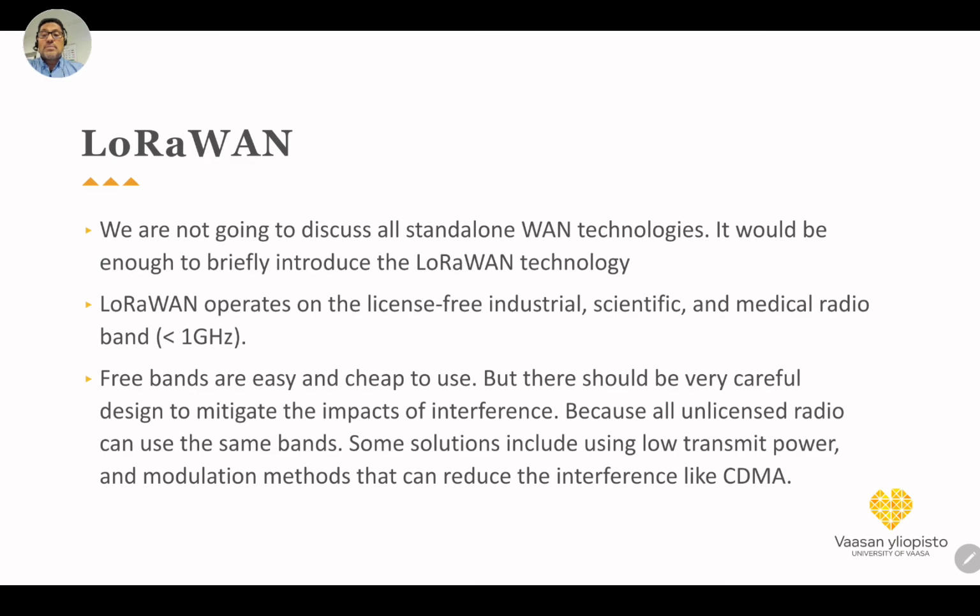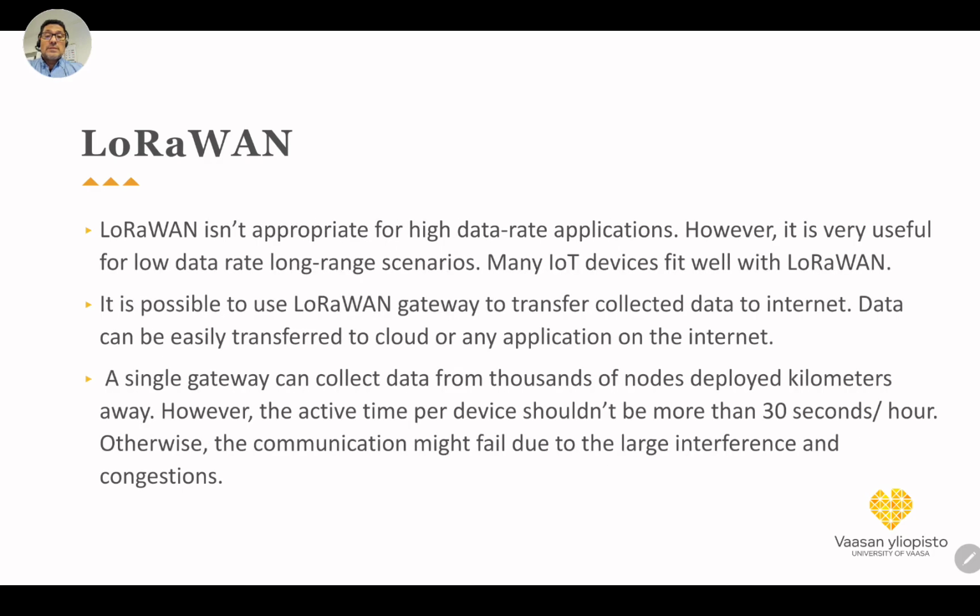Yes, this is now a little bit about this LoRaWAN. So it is long range wide area network. As I said, they use this license free industrial, scientific, and medical ISM bands. The modulation concept used in this LoRa technology is CDMA. So they can separate between users by using spreading codes, the orthogonal spreading codes in the uplink and in the downlink, and also between different devices.